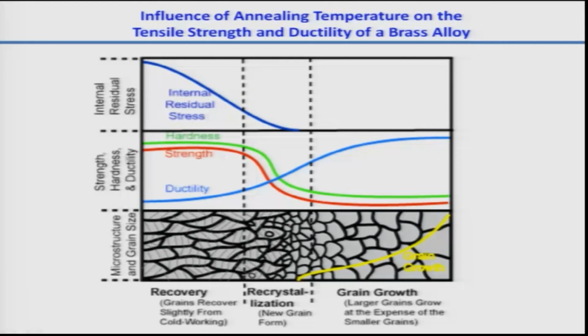Same thing is shown here. As you know, any material, if you deform, material is a continuous thing. That means the grains are continuous, they are attached to each other. So now you are putting a stress into the material. As the grains are continuous, if you put a stress, the only way they can remain in touch with each other is by deforming them or generating some kind of stress inside, and this stress which is generated is known as internal stress.